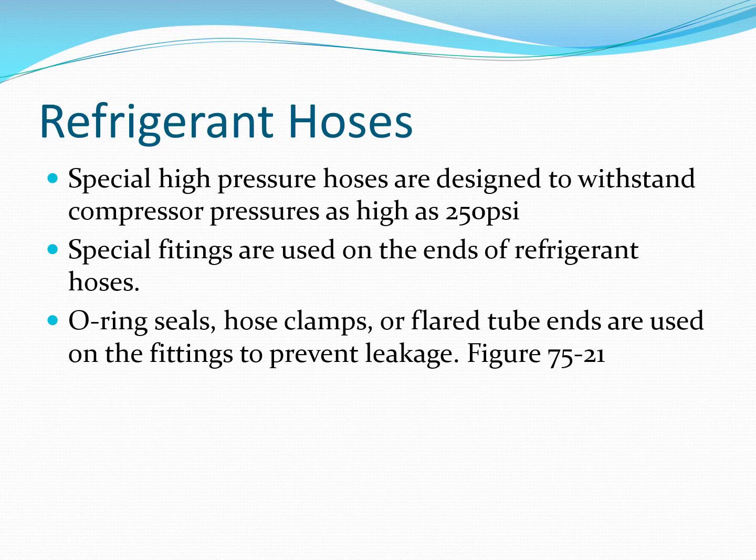If you are making repairs to hoses, it is not recommended to just cut one off and install it with a hose clamp. That is not a recommended practice. It's not if the system will leak, it is how much it'll leak. It will leak if you're using hose clamps on a new system. The pressures are just too high.